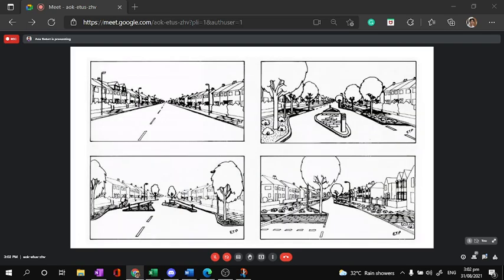So, usually in a village area or residential area, a road network is very unsafe for children crossing, or in residential areas, private cars cross the road. What you can do for this space is intervention: a traffic calming device. You put an island, narrow the section to slow down the vehicle before it enters the subdivision. So this is an island control. This is a narrowing of the road. You put two islands so the lane is divided and therefore the vehicle slows down.